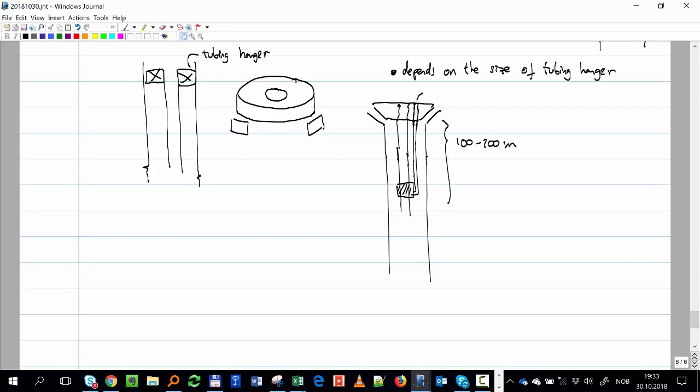So that's why they decided, many years ago, especially after the war in Kuwait, if you remember, there were some images of wells just burning, a bunch of wells in the desert just burning. So they introduced this subsea safety valve, where the hydraulic line always has to keep it open, always. And when that's not connected, when something happens, it's going to close.